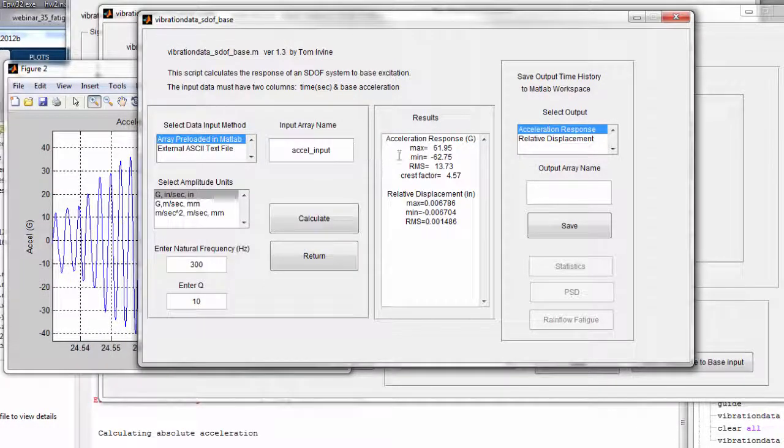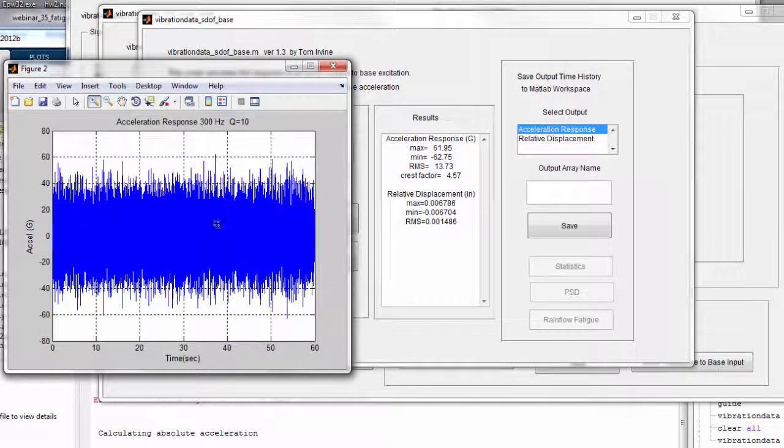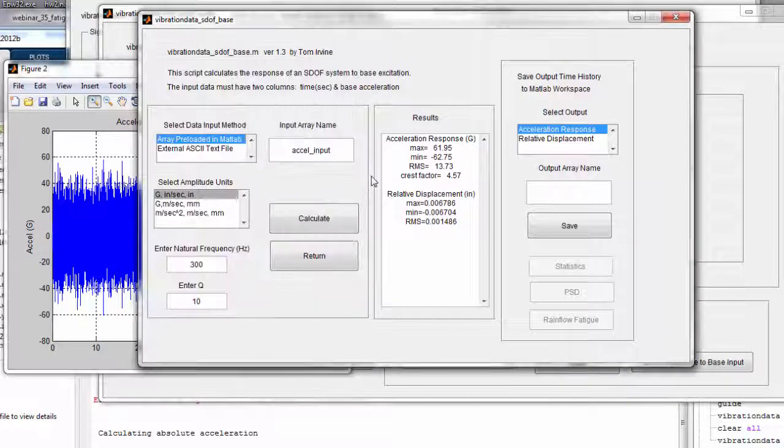Let's go over here, and this is just some quick look statistics. The RMS value is about 13.7 GRMS. Now, the mean value you can see is approximately 0. In fact, if we go back to the, okay, where is it? So one of these things will say reset view. Where'd it go? Reset view. It's under tools. The mean value is essentially 0. That means that the standard deviation and the RMS value are the same. I'll show you the formula shortly, but we've covered it before. So sometimes we get a little bit lazy and we'll use 1 sigma standard deviation and RMS values interchangeably.